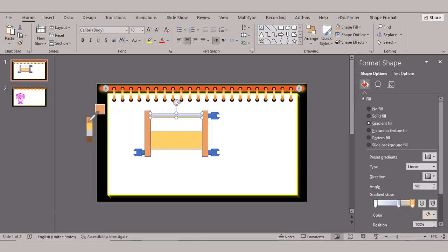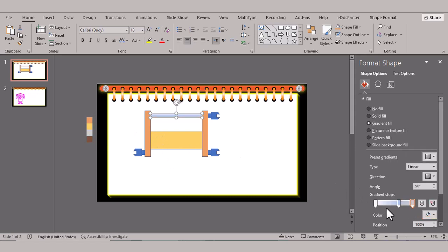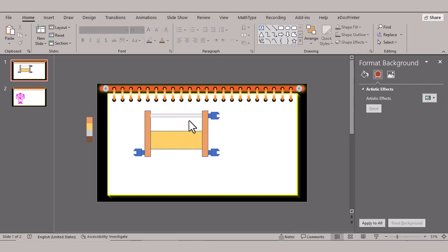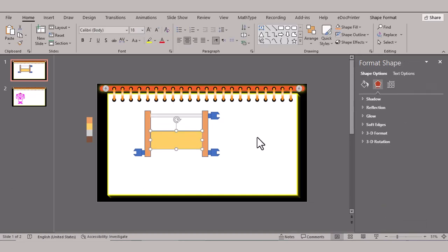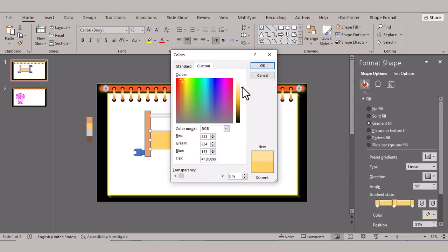It should be noted that a rheostat does not change voltage directly, the applied voltage remains constant across both component and circuit, unlike in a potentiometer. Instead, a rheostat adjusts current, and thus in effect voltage, by increasing or decreasing resistance. Precisely how it does this will depend on the type of rheostat resistor being used.